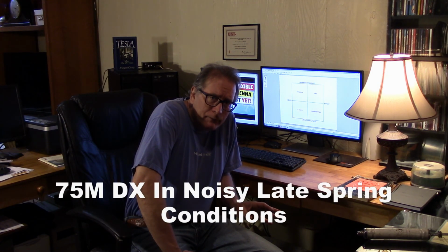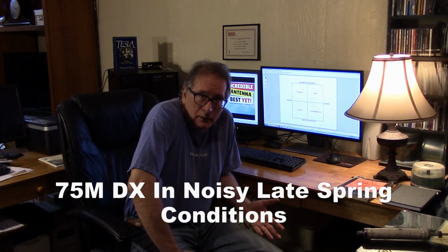So do you want to, for instance, have DX capability in the 160 meter band, or maybe the 75 meter DX window, or 40 meters? It's going to be a little more difficult, but we can get a low angle radiator for DX performance in those bands. And the way I chose to do it was with vertical antennas. So I'm agreeing with the DX Commander. I think the vertical is the quickest way to get there.